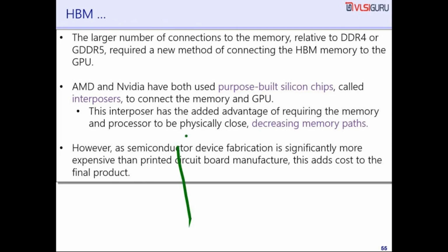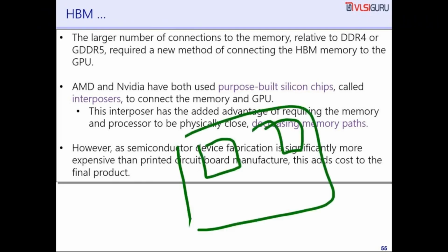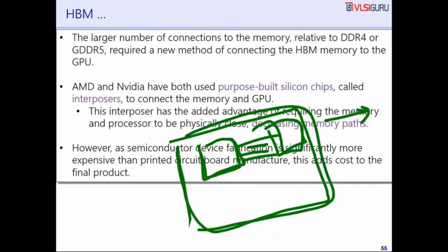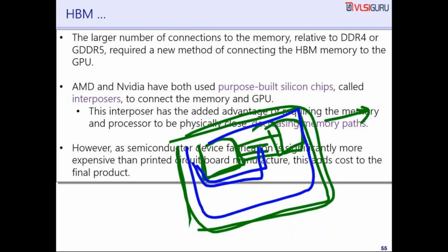So you have got a circuit board where you have various components connected on the PCB. Now all that we are doing is establishing this connection at the fabrication level only, by having one more layer called a silicon interposer in between, through which we take the connection. Now you may say, why can't we do it on a circuit board itself? The whole point is that manufacturing the connection there could be a difficult job, and it may end up having multiple connections overlapping, which cannot be done properly.